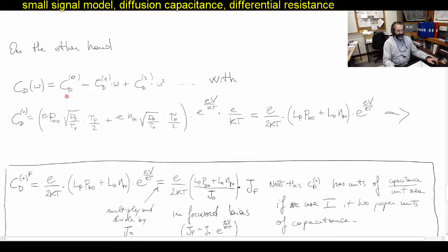So, what is the first term? Well, the first term we can demonstrate is this thing. All these are constants, and then the term that depends on the specific quiescent point we are working at on the nonlinear curve of the component, times e over kT, which we can rewrite in a more concise way using LP and LN, the diffusion lengths.